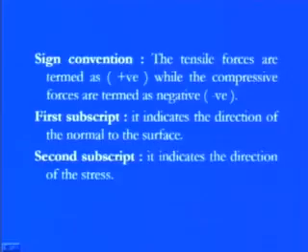So we can use the sign convention for the tensile forces or tensile stresses as positive, while for the compressive, because it tries to oppose the tensile way, that means we are now compressing the object. So obviously whatever internal forces are set up within the object, they always try to repel that part. The resistive forces are directed towards the outside of the object. So because compression is there, we need to choose the compressive forces, or the compressive stresses, as negative.